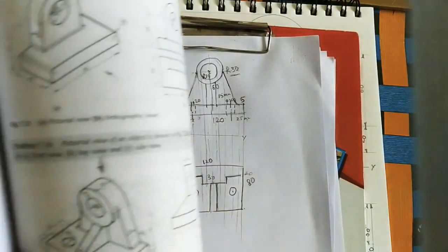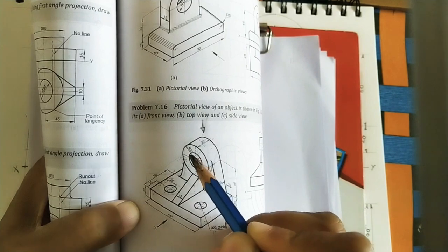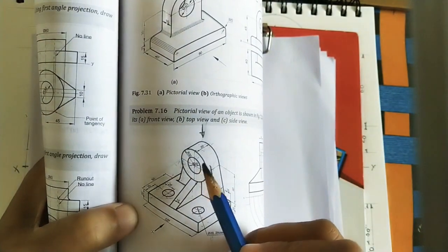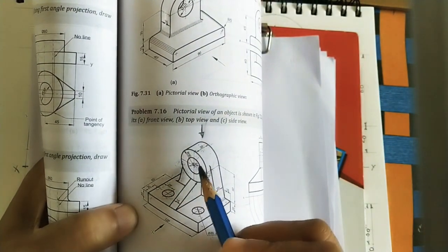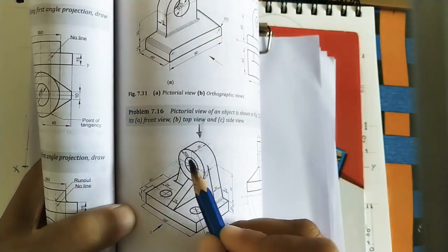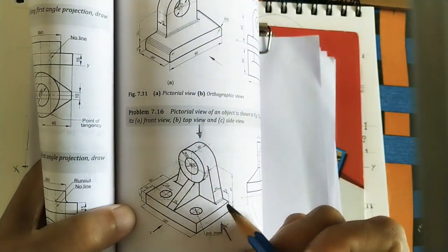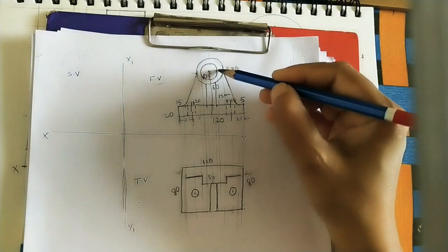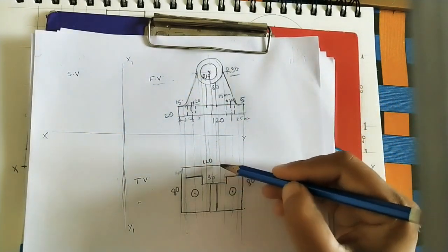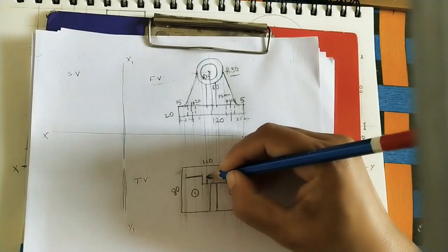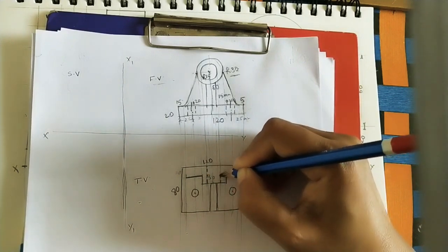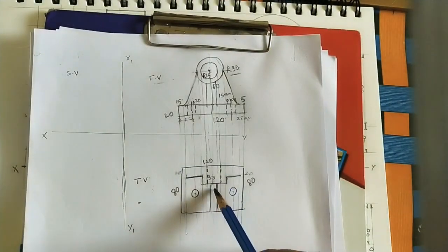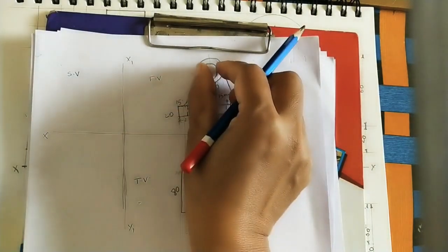After getting this view, in the top view we can't see this circle inside this bigger circle, correct? This is a circular hole inside this part, correct? But this is invisible. We have to show this invisible part inside this thickness. Now here we have to take the invisible circular hole. From this smaller circle, whatever projector lines are coming, I already did roughly here. Wherever these lines are passing, we have to take dotted lines. Make this part dotted because it is the invisible hole inside this thickness. In this 30 mm thickness, these are coming from the smaller circle, correct?